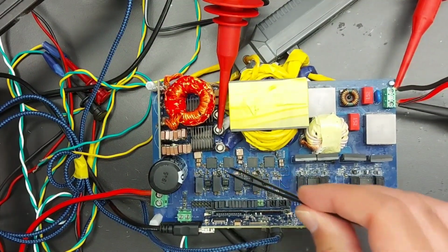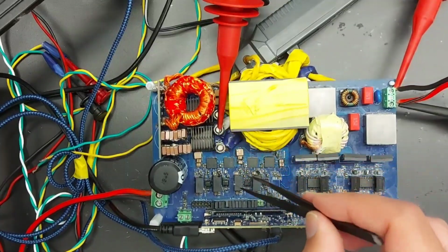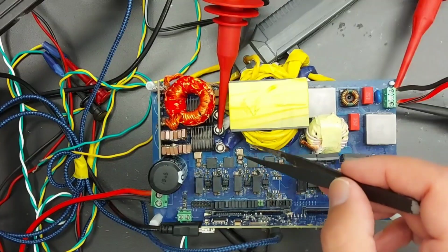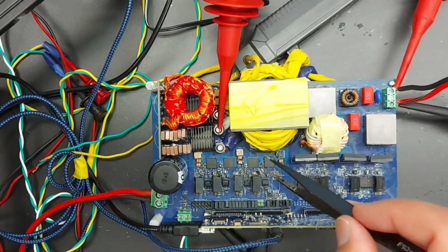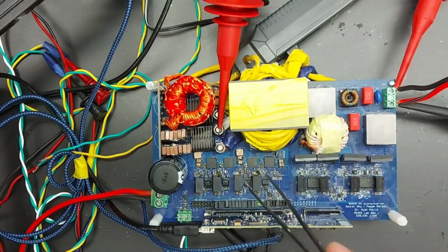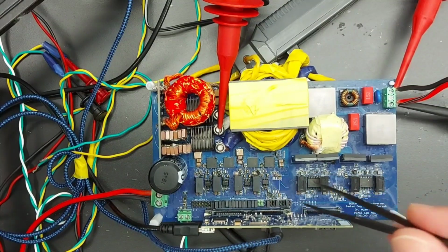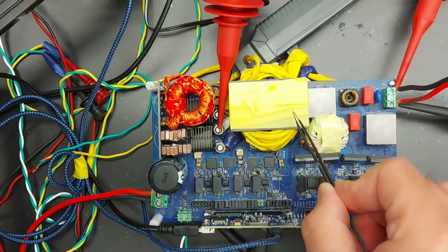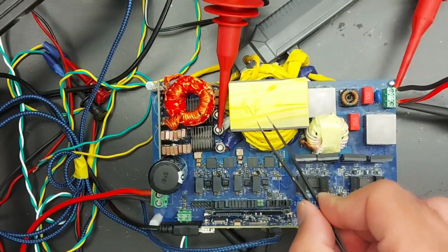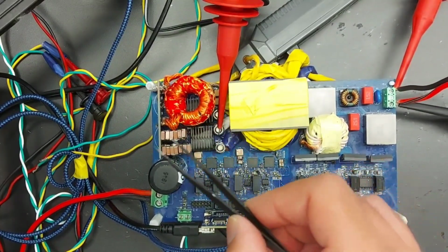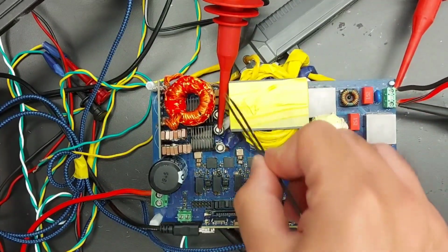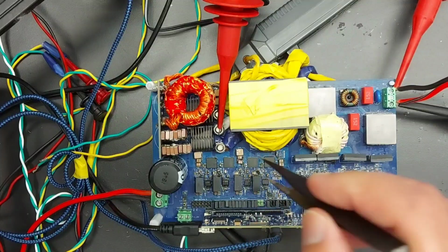But here, for the primary and secondary of a DAB, we have to use GaN devices because we are switching at 100 kilohertz. So in order to reduce the switching losses, we have to use these GaN devices. As I have mentioned earlier, we have to optimize the value of the transformer turns ratio, the value of the power transfer impedance, which is realized by the leakage inductance of a transformer or an actual inductor in some designs, and the capacitors. So this design is already